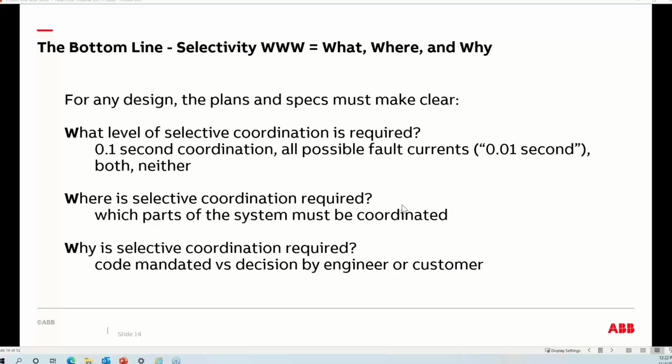Where is the selective coordination required? Well, a lot of you will probably say, isn't that obvious just from knowing electrical systems? In many cases, it is. So for example, if you're using labels like ATS-LS, LS is interpreted as life safety, ATS-LRS, legally required standby, that certainly makes it easy to pick out which systems the coordination requires. But I have seen drawings that use ATS-A, B, C, D, etc. And then what's the vendor to do?